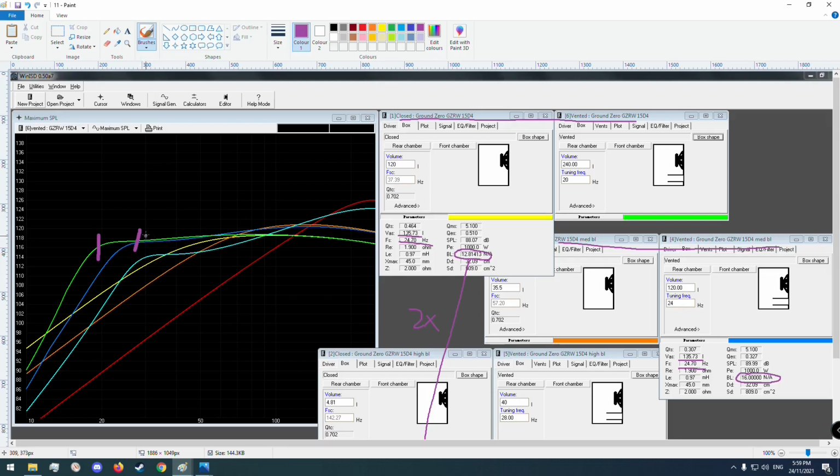But you can see this one starts to roll off just below 30 Hertz. It's really hard to see, but this line right here is 30 Hertz. It'll probably be completely gone once this is rendered. But this one, the green line, rolls off after 20 Hertz. So you get about 10 Hertz extension from having a lower BL and a larger box.